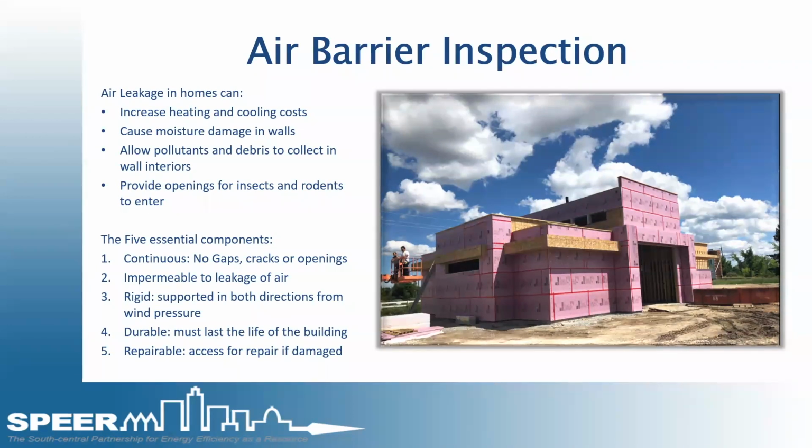Air leakage in the homes is increased. It can increase heating and cooling costs if it's not done correctly. It can cause moisture damage inside the walls. It allows for pollutants and debris to collect inside the interior walls, also providing openings for insects and rodents to enter the building if they're large enough.